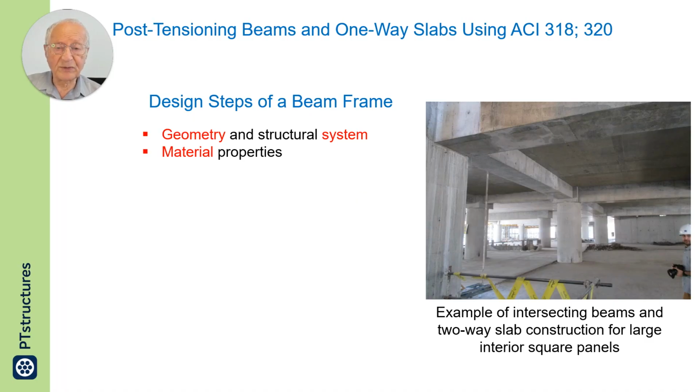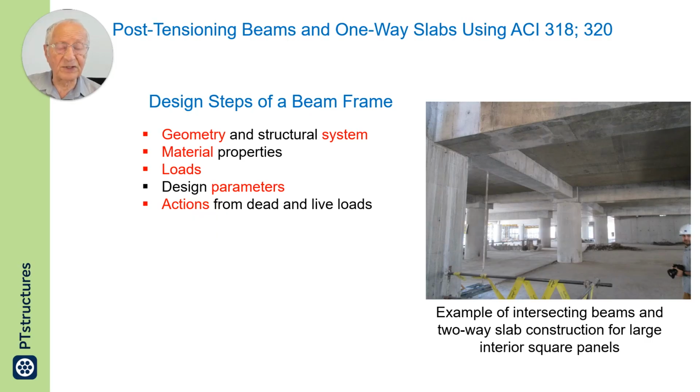After geometry, we define the material properties, define the loads, define the design parameters, and follow it by calculating the actions, dead load moment, live load moment, and the reactions. Subsequent to that, we go into post-tensioning definition.